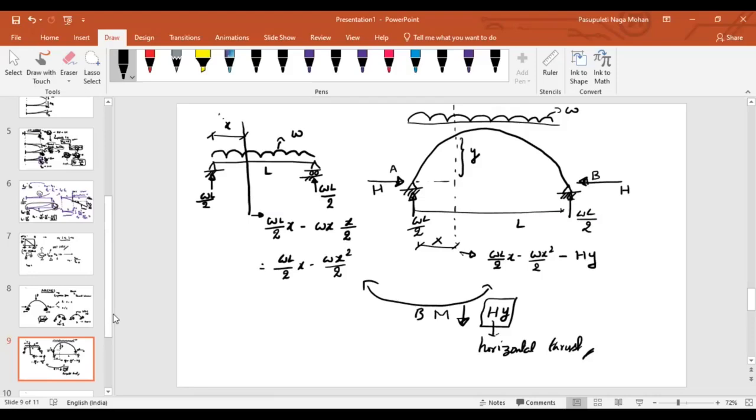By keeping all those things in mind, it also depends upon the length of the span. If the length of the span is not large enough, then constructing an arch might not be an economical or efficient option. So to decide, one of the main factors is the spacing between the columns, or the spacing of the span.